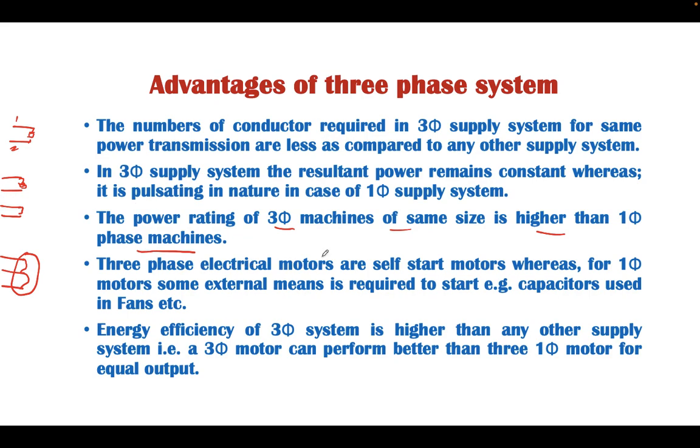Three-phase electrical motors are self-starting, whereas single-phase motors require some external means to start. For example, the capacitor used in fans. At our home, we are having a fan, and there is always a capacitor in the fan. If we remove that capacitor, the fan will not start.